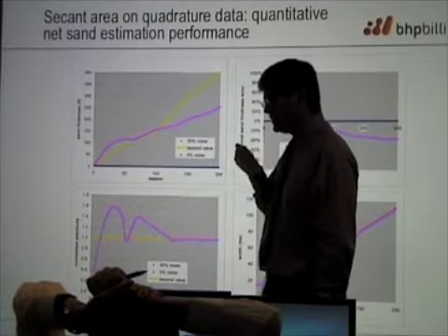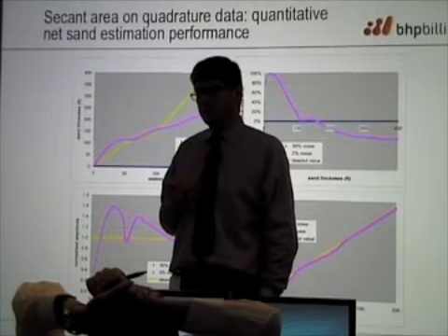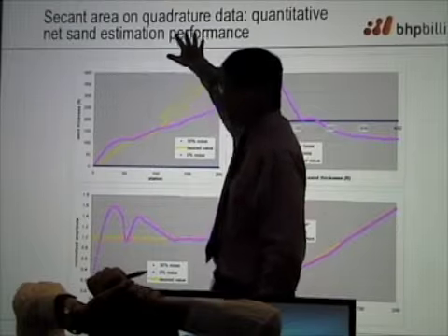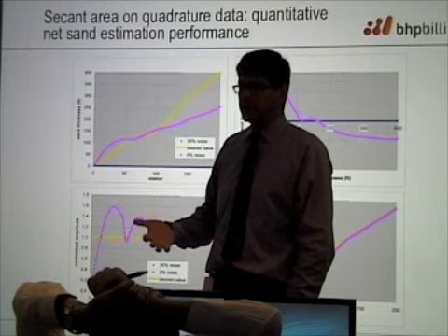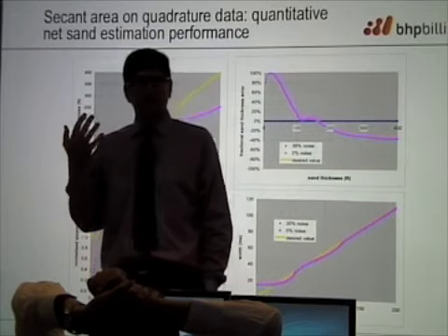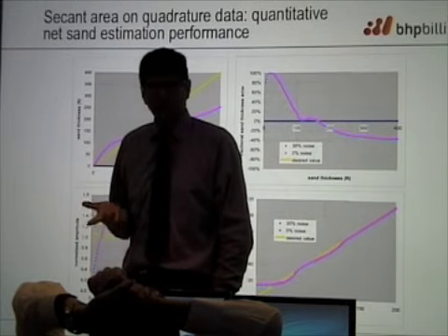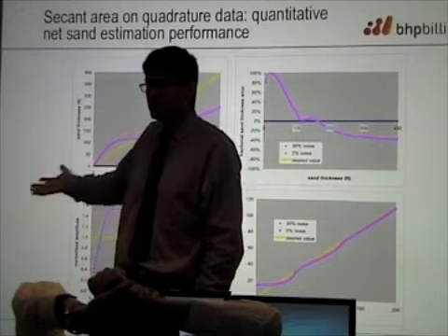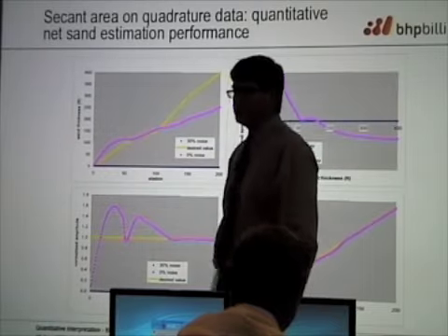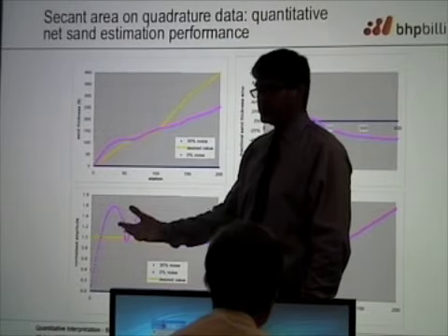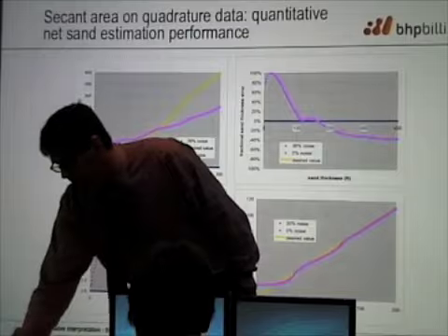And this has more high frequency, and many people will say, I like this, because why am I going to put a 6 dB per octave high cut on my data? That destroys high frequencies. You should do it, though, because all you're doing is artificially adding high frequencies here that cause you to get poor performance in estimating what you need to estimate, okay?